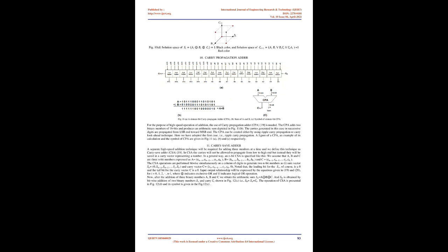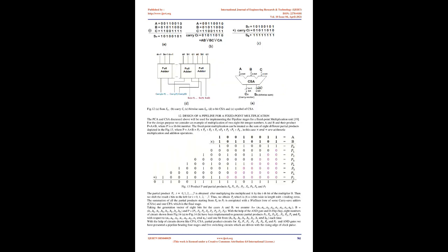for negatively weighted inputs. Every threshold gate is augmented with an inverter/buffer. The function of the inverter/buffer is to invert the output of a threshold gate. The logic function done by the buffered threshold gate is the inverse of that done by the threshold gate itself. For the rest of our discussion, when we refer to a logic function such as AND, we imply the logic function performed by the entire gate, i.e., threshold gate plus an output buffer. The parameters used for the implementations and simulations of different gates like AND, OR, NAND, NOR gates and other combinational or sequential circuits are given in Table 1. 6, 7.